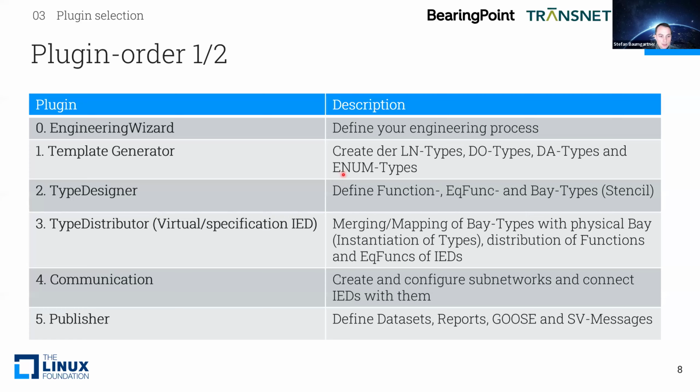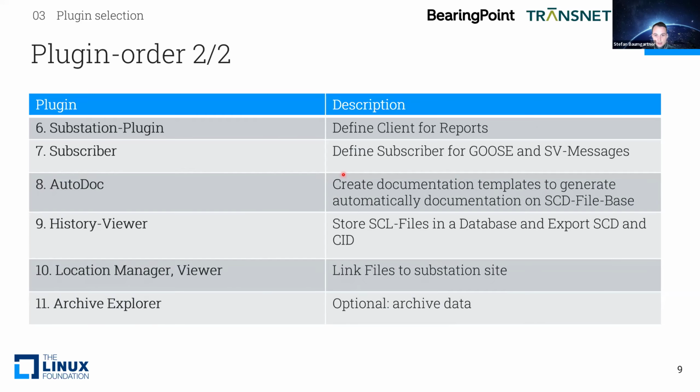networks and IEDs. And after that, we can create our communication, talking about the publishers. We can define our data sets, the reports like buffered, unbuffered reports, the GOOSEs, and the sampled values. After that, it's possible to subscribe or define the client for the reports. And after that,